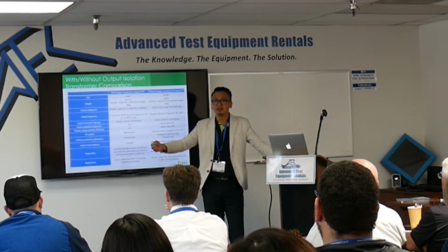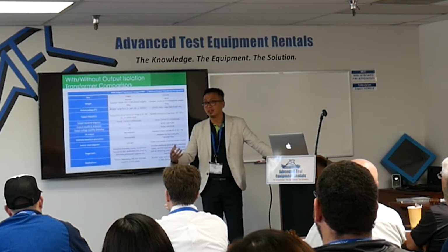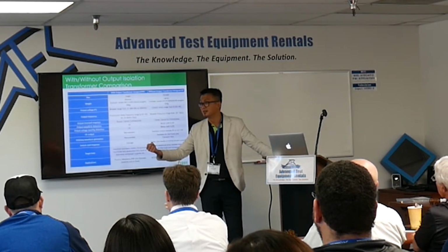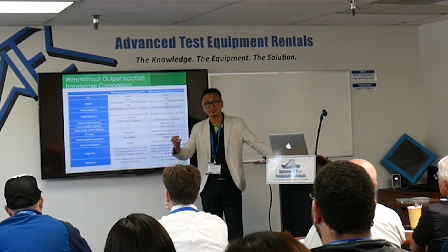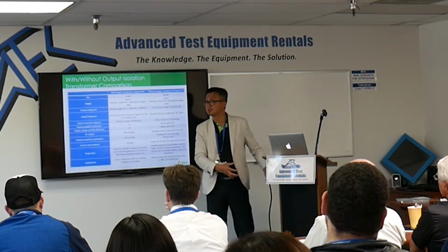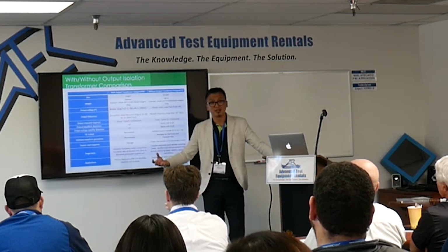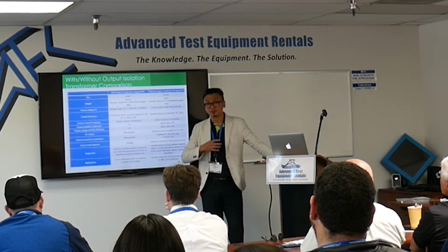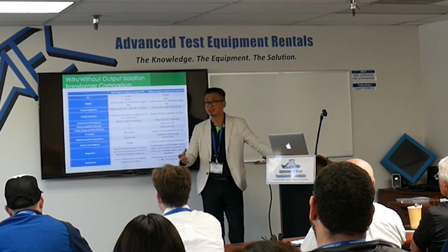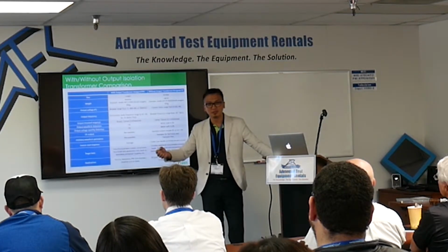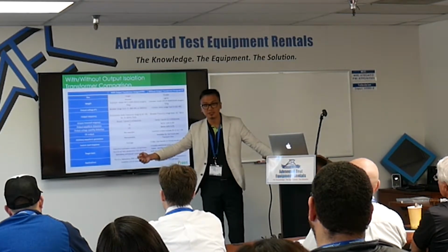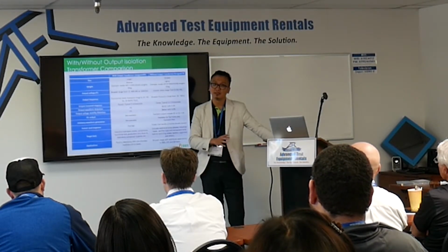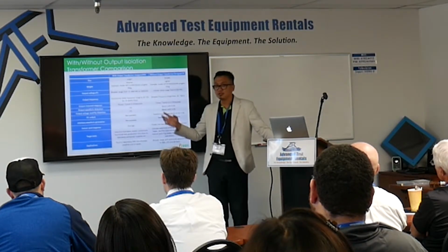Because in your factory, there are a lot of motors, and you never know what the testing load is. So if you're using high frequency, commercial, like your PC UPS, in your production line, or testing motors, testing home appliances, you will damage it very quickly, within 2 years. Because if your motor gets stuck, the reverse current comes back, and you will damage your power supply or UPS very quickly. So the isolation transformer